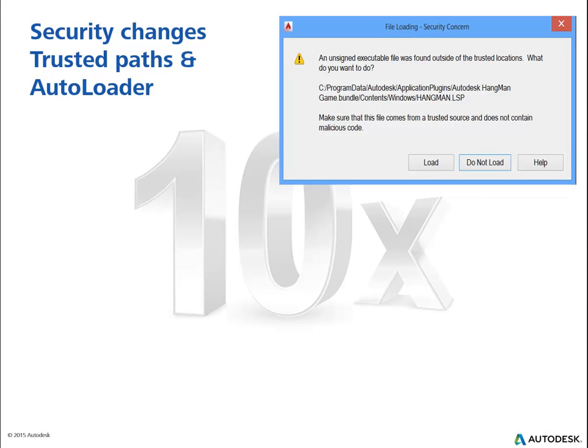The major changes we have are on the security piece, on when the application, the DLL or Lisp or C++ DLL code is loaded. Before, we used to have this message, and the way to avoid it was to place the application inside the applications plugin folder.